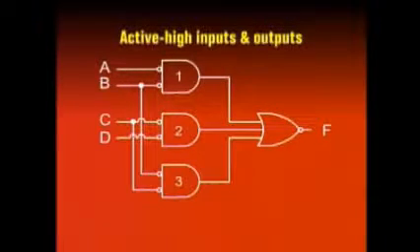By modifying the circuit to have active low inputs and outputs, the circuit sets the output F to active 0 to indicate detection of adjacent ones. Since the inputs are also represented by active low, therefore the input ABCD equals 0, 0, 0, 0 actually represents 1, 1, 1, 1. Similarly, ABCD active low input 0, 0, 0, 1 actually represents 1, 1, 1, 0.